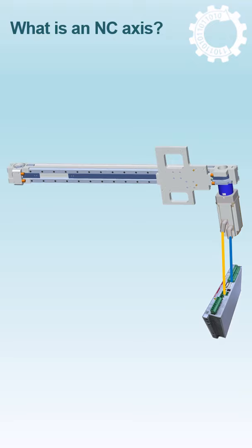Next, we are going to add two inductive limit switches on both sides to limit the travel path and avoid often bumping, which can damage the machine. The limit switches are usually connected on special inputs of the servo drive as normally closed switches to detect cable break. Each time a limit switch is activated, the drive controller issues an error and stops the movement.